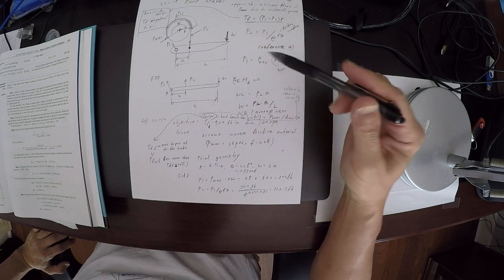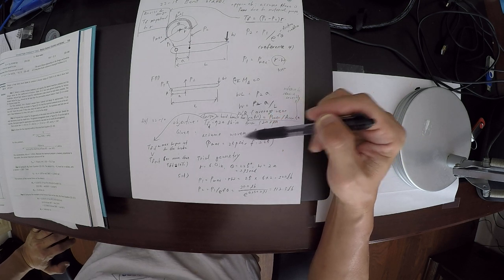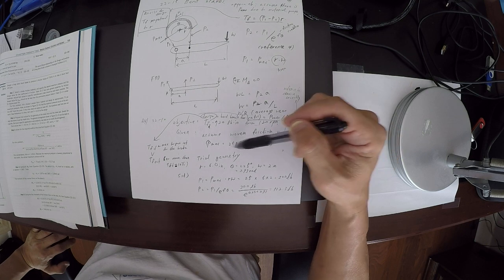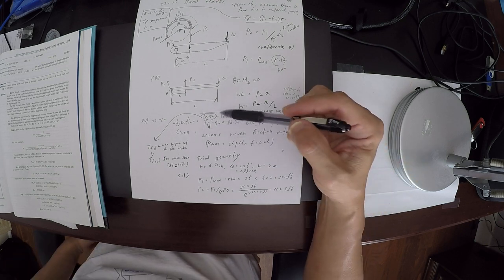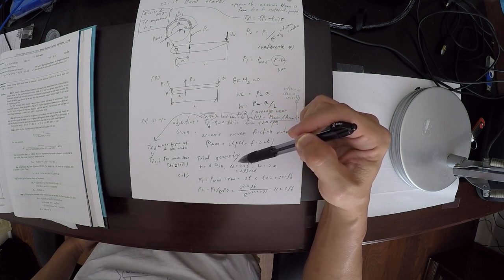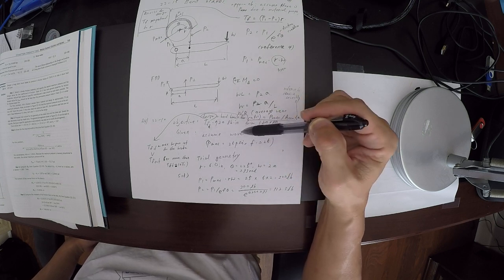So assuming it is a woven friction material with the Pmax that it can handle of about 25 psi, and the friction f is 0.25. That's the given property of the material. So when it comes to design, again, we need to know some geometry, without having any basic data right there.